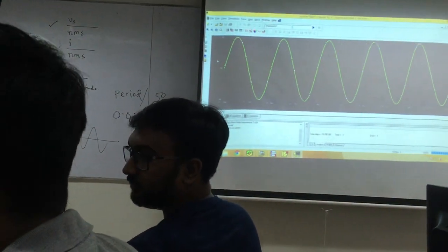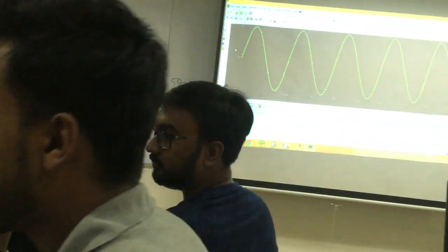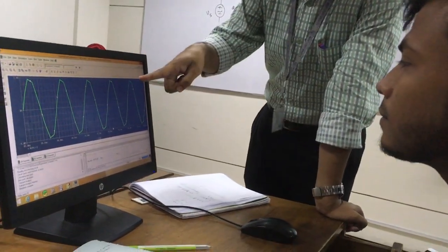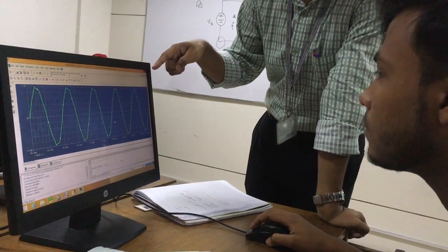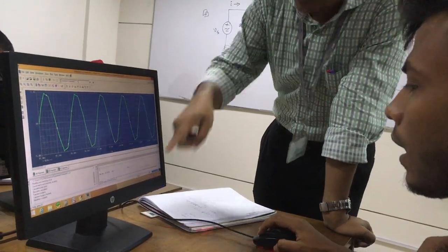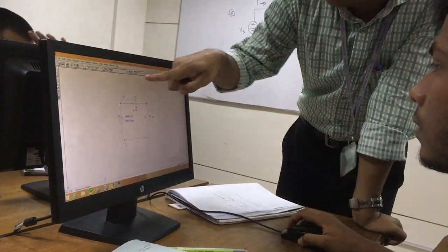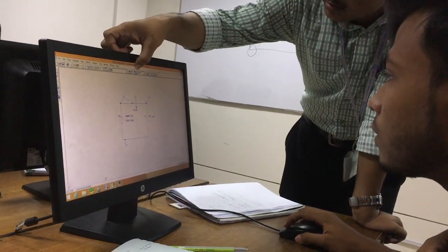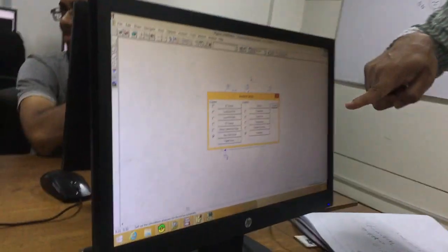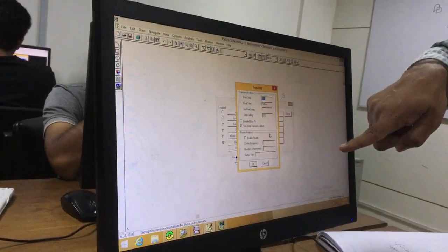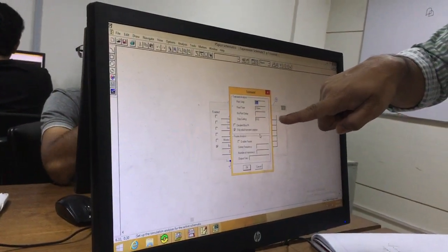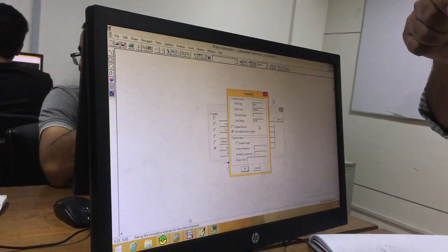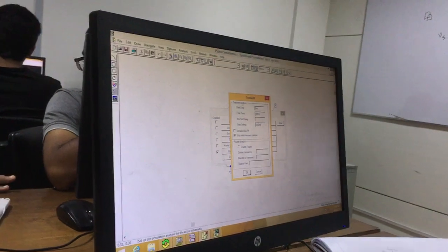It's okay. What's the problem with it? But I think you didn't go for what do you call step ceiling. Can you please go here? Click there. Not there. Here. Yeah, there. Setup analysis. There. Transient. Why is it 0.02? Where is the milli guy? 0.02 ms milliseconds. Milli is not there. We are working in seconds.